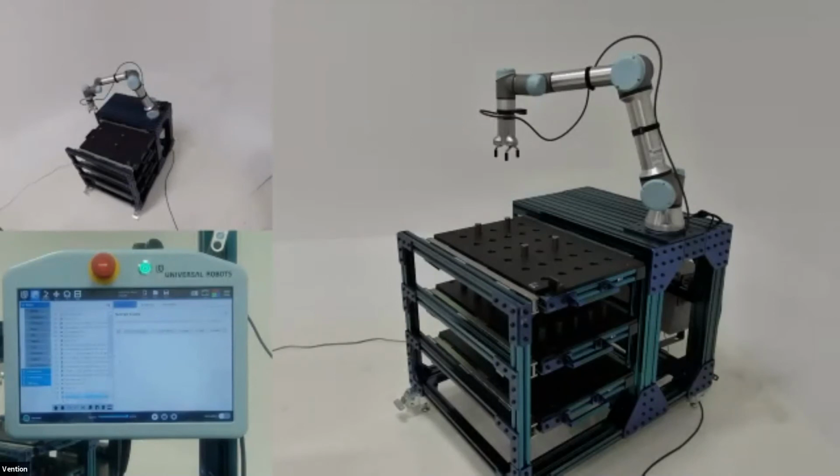From here, I will give a brief summary of the topics covered before we move on to the question and answer period. First, the waypoints, which are the points in space that you would like your robot to travel to. Second, the robot commands, which are threefold: the robot loop, the ability to add a robot path, and the ability to execute one of those paths that you've created. After that, the robot reference frames, which are used when creating your path. Then the ability to calibrate your robot both on the cloud and the live portion, and how easy it is to deploy your robot path program created in MachineLogic.